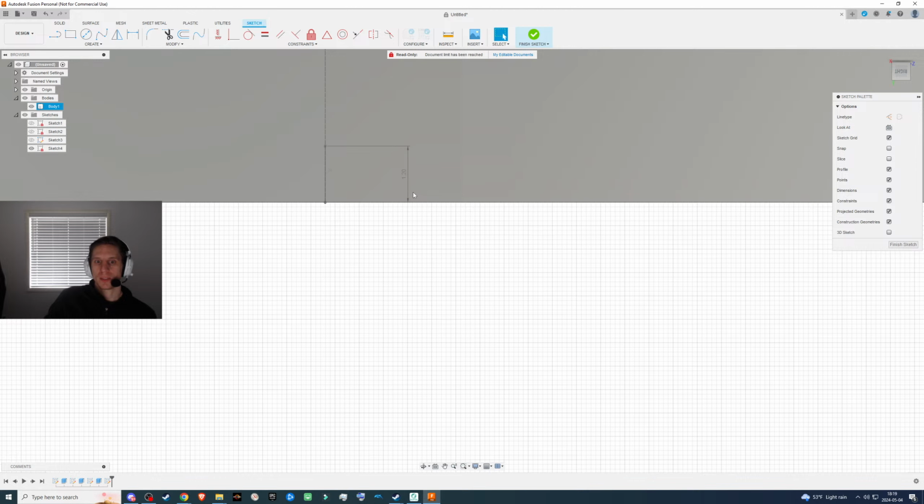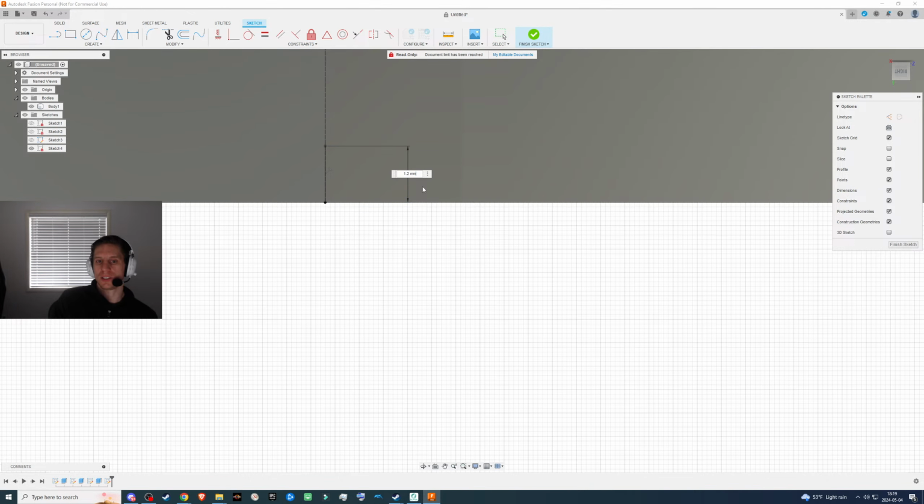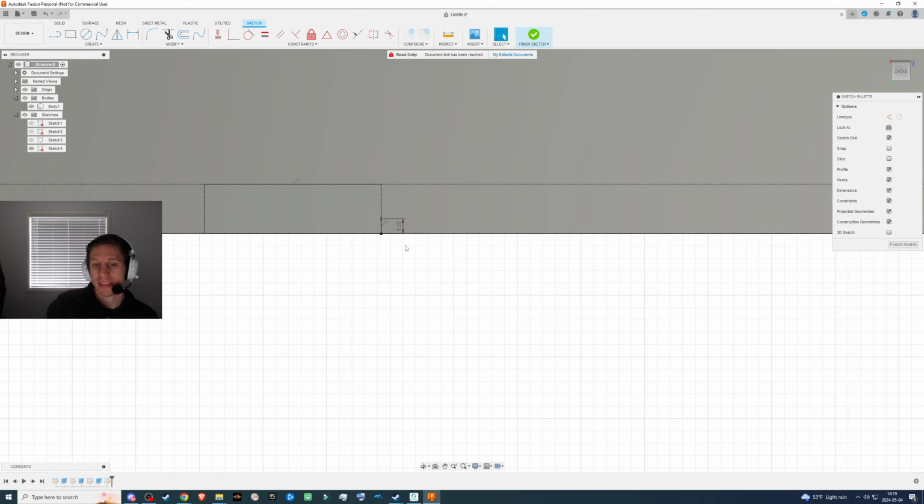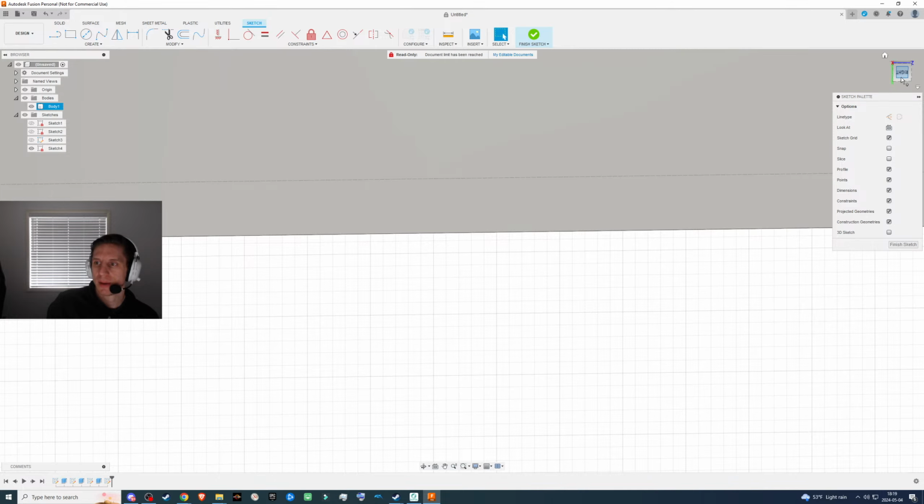That's useful. And we couldn't really do something like 1.25. If we're printing 0.2 at a time, it's going to get to 1.2 and say, okay, we need 0.05 more. Let's just not print anything and move on to the next layer. So yeah, that's a decent amount of detail.